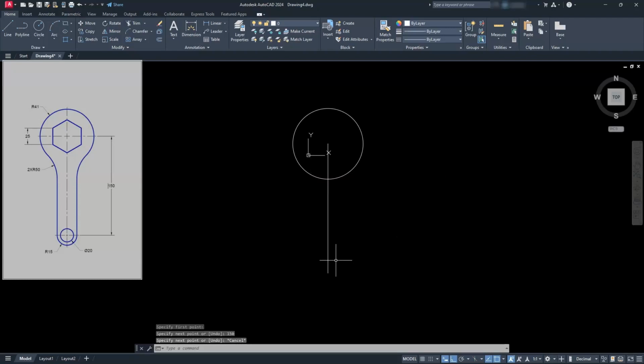Alright, I need to figure out what the offset here is, and the radius of my overall thickness here should be set to 15. So that's also the offset distance that I'm going to need. So I'm just going to go to offset. I'll go ahead and type in 15. And then I'm going to offset this line, one to this side, and then one to the other side.